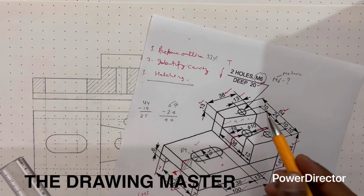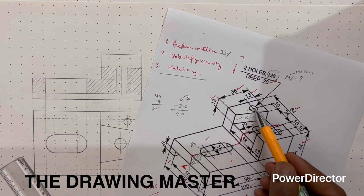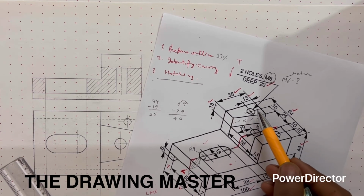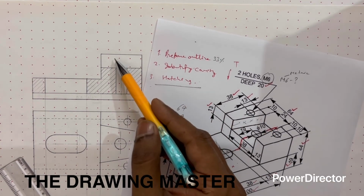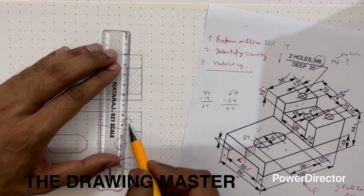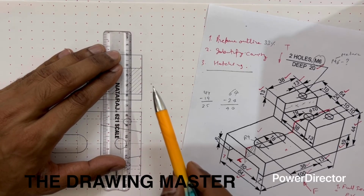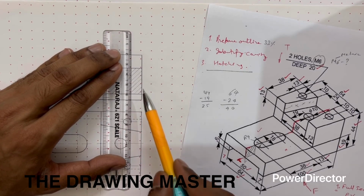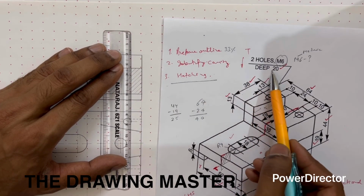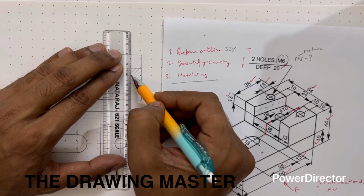One more thing is there. In the front view, if you want to show this hole as a hidden hole, you can draw it. If you think this is important to represent, you can use the hidden line here also, right? Simply I'm telling you the procedure. Here is the position of the hole. To take the projection lines, it is given that the depth is 20 mm. So from here this is 10 and 20.